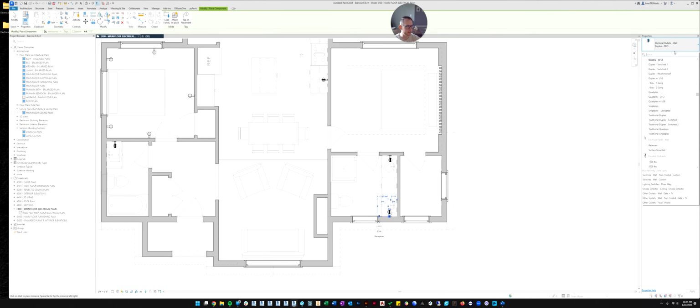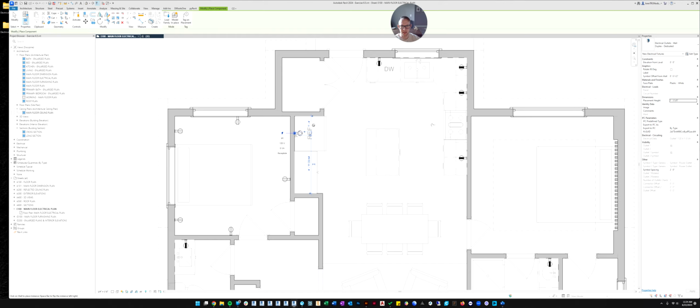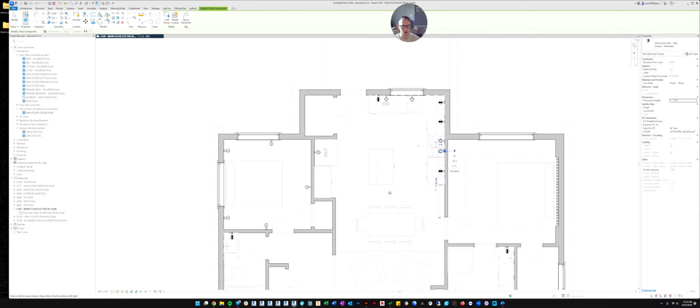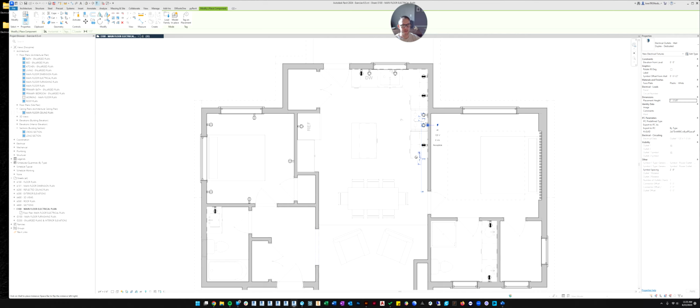All right, let's do another type. There's something called a dedicated duplex. So in electrical work, big appliances like the refrigerator, the dishwasher, the garbage disposal, and the range, so here we have a range, and then we also have the hood for the range, those all need what's called a dedicated outlet. So they're the only outlet on the circuit.